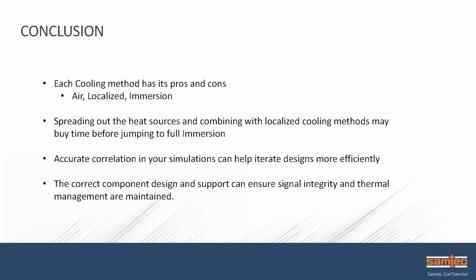In conclusion, each of these cooling methods has its pros and cons, from air cooling to localized cooling to immersion cooling. Spreading out the heat sources or combining localized cooling methods may buy you time before you have to jump into full immersion cooling. Accurate correlation with your simulations can help with the iterations of your designs and make them more efficient so that you don't have to iterate them time and time again. The correct component design and support can ensure signal integrity and thermal management are maintained.